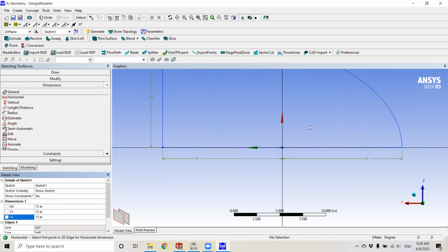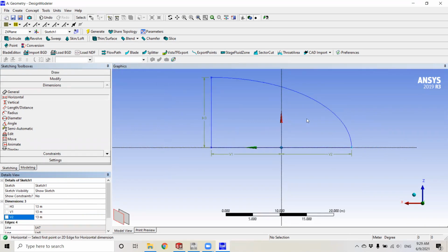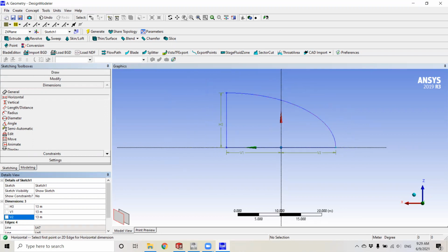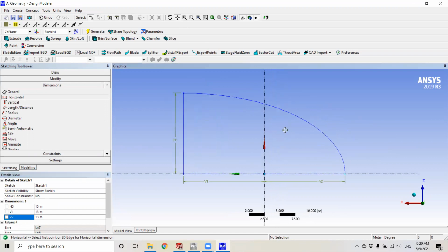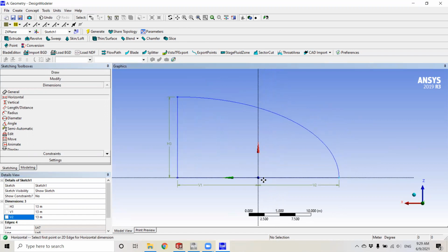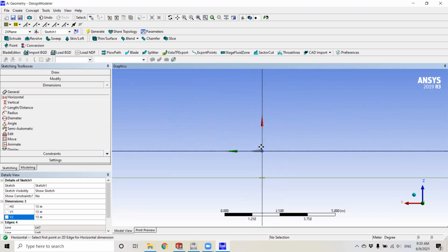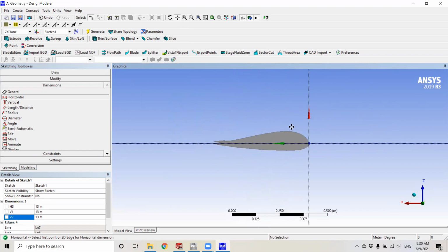Well, there's a lot of divergence of what an adequate fluid domain size would be, and I'm going with 25 times the maximum body length. This airplane has a maximum body length of roughly 0.5 meters, half a meter.